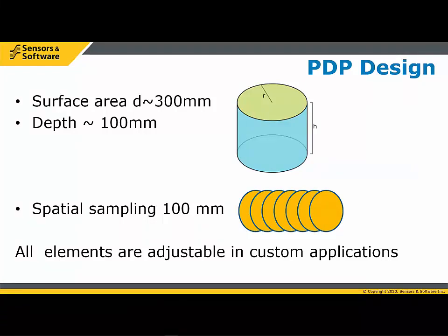We don't normally do that in real time. In some of our devices, we do it. The trick is to be able to have all of the data together at the same time to build the map image, and we call that grid mapping in a lot of our products. You'll actually put a number of lines, traverse them, and build the map in real time. With the PDP, it's been a question mark as to whether that was a primary use. So what we do is we just collect each line as an independent line and then export it and use one of our mapping tools to build the map.